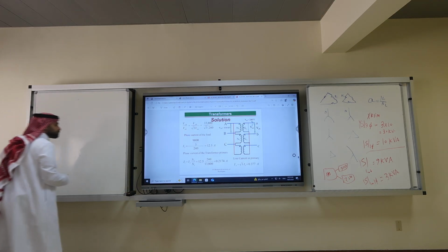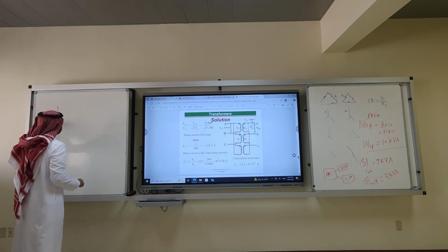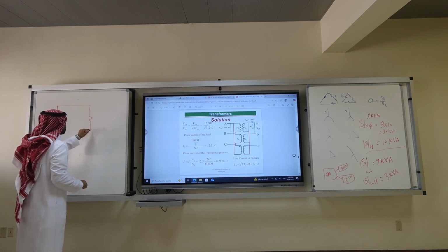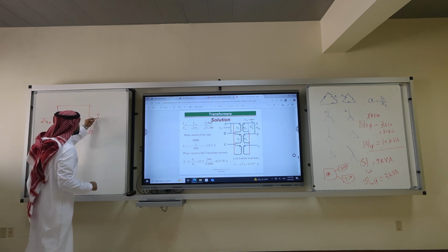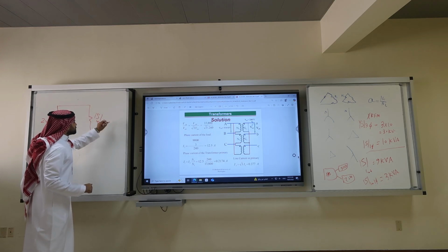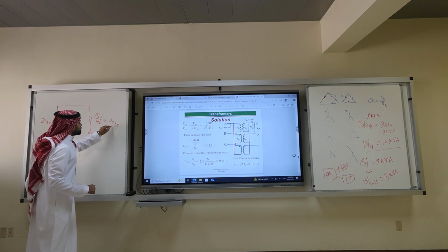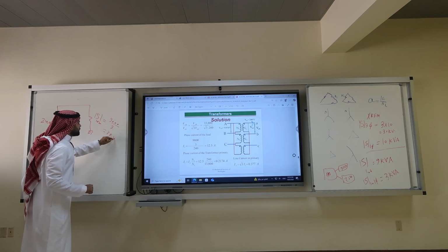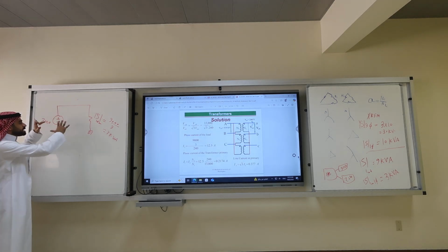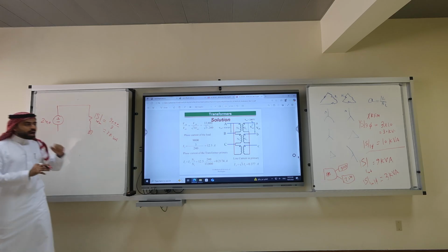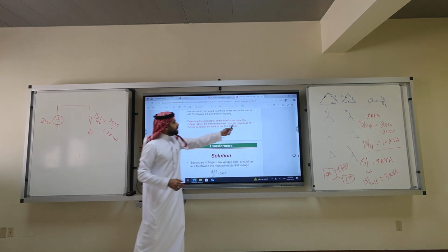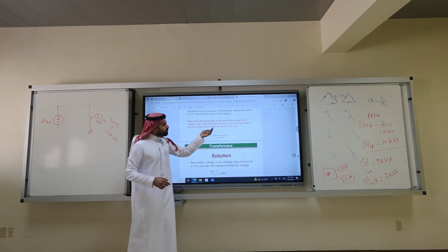So in reality, I'm saying 240, and I'm having a load. This load has S, one phase load, to be what? 9,000 over 3, which is 3 kVA. You agree with me? I explained it to you. I'm converting. I'm getting a calculation for a single phase circuit. Why? Because he asks the question: find the magnitude of the line current of the bank.